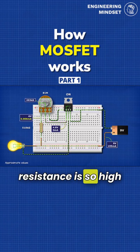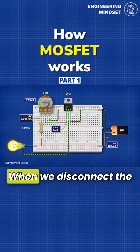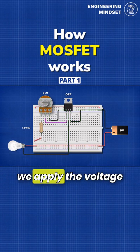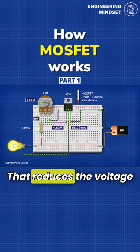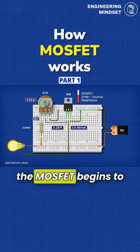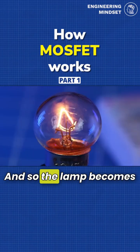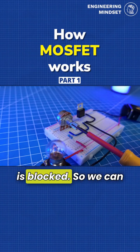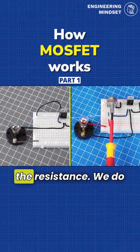The resistance is so high here that almost no current flows through the resistor. We just get a voltage. When we disconnect the power to the resistor, the MOSFET drains through the potentiometer. If we apply the voltage again, we can rotate the potentiometer to increase the resistance. That reduces the voltage available at the gate. As the gate voltage reduces, the MOSFET begins to deactivate, increasing the resistance between the drain and source. And so the lamp becomes dimmer and dimmer until the MOSFET completely deactivates and the current is blocked. So we can turn a circuit on and off, or we can vary the gate voltage to vary the resistance.